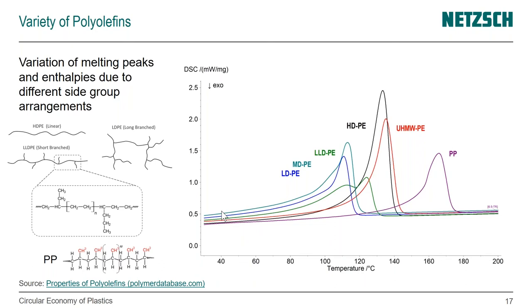out of databases. That is slightly different to the FTIR method, where a database is part of the package, where you always want to compare this fingerprint to all the values in the database. For DSC, we have a database of over 1,000 different grades of materials, but we don't have a database of all different kinds of UV stabilizers and other things.